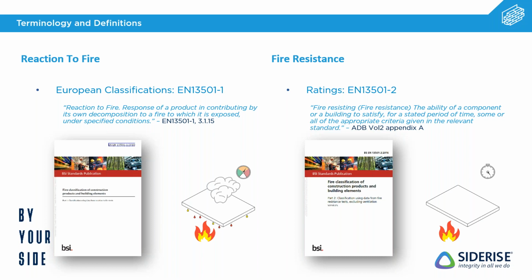Reaction to fire, just as the name suggests, is all about seeing how the product actually reacts when it's exposed to that fire. All materials will eventually break down when exposed to fire. The important thing from testing reaction to fire classification is to see how severely they break down, how quickly they break down, and what kind of volumes of debris or smoke they produce as they're breaking down. So with reaction to fire, we're splitting them into different categories as to how reactive they are, how much they're going to contribute or not contribute to that fire.